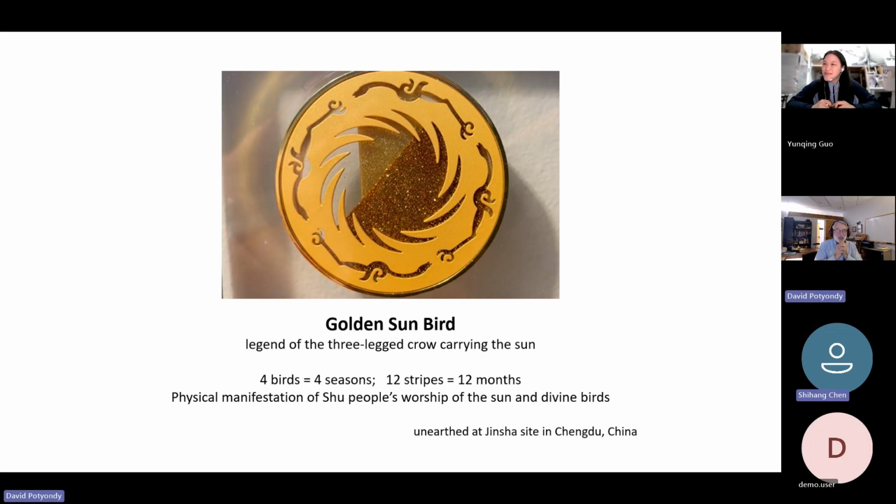So I refer to that as granular material, and the behavior of granular material is very sensitive to the shape of the grains and the size distribution of the grains. And then there is a very simple force displacement relationship that happens when two grains push together. That very simple one we're going to learn about, and that's one of what we call contact models in PFC.